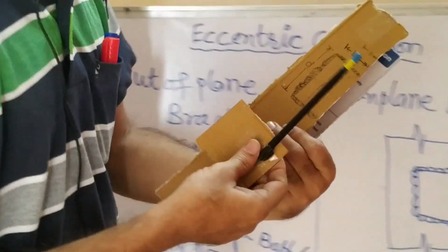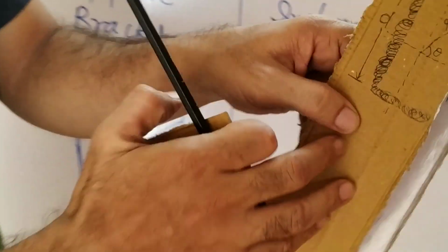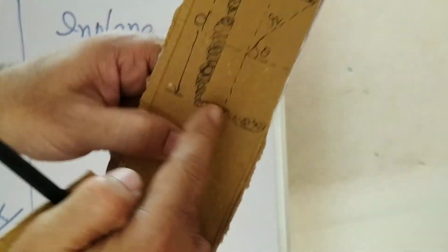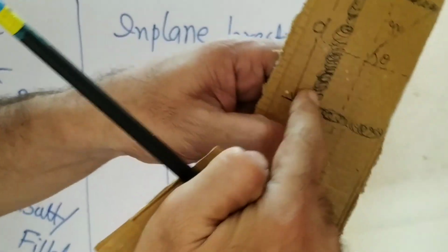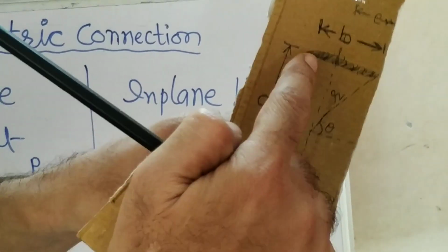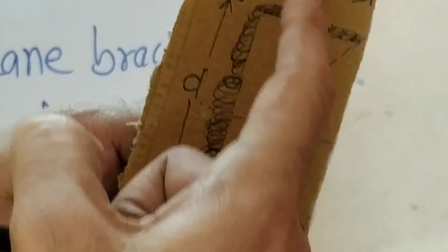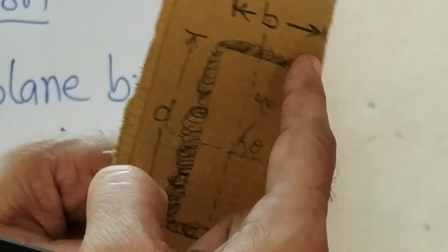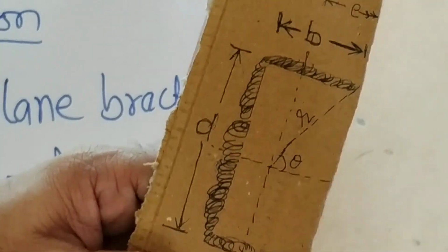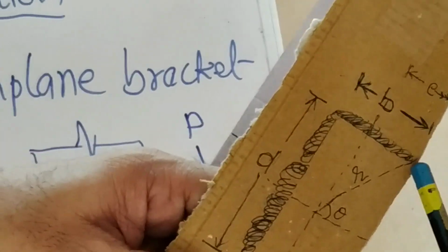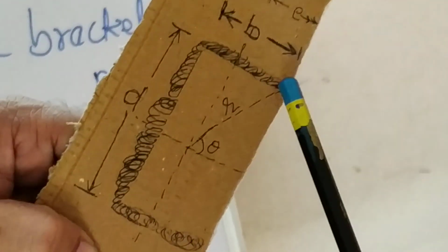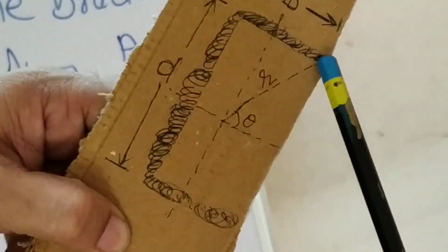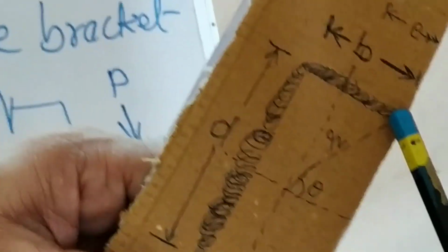So if you look carefully at the in plane, this is the C-shape welding, the width is B, the depth is D. Then we have to find the centroid of this weld group with the shape of C, and this extreme point will be subjected to a twisting stress, which is a shear stress due to twisting, and the direct shear stress.